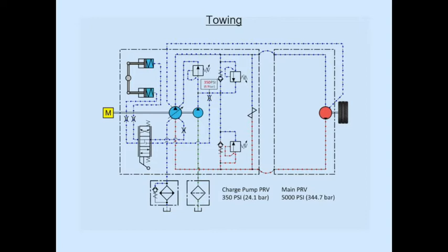So you've got to be really, really careful that you obey the manufacturer. And never tow with a cable or a chain. Nothing that can recoil. The problem, folks, is there's been a lot of people that got hurt because what they'll do is as soon as they disconnect the hydrostatic transmission, and let's say they're hooking it onto a towing vehicle with a cable or a chain, and it's a little downhill. As soon as they disconnect the hydrostatic, it's done. It's going to run away.